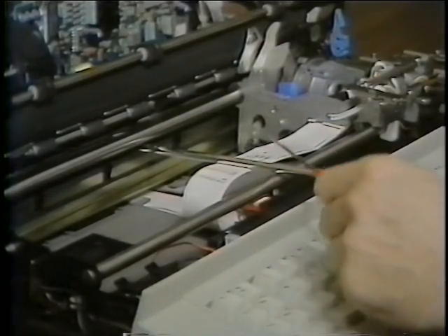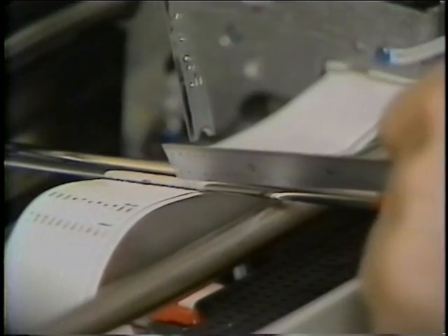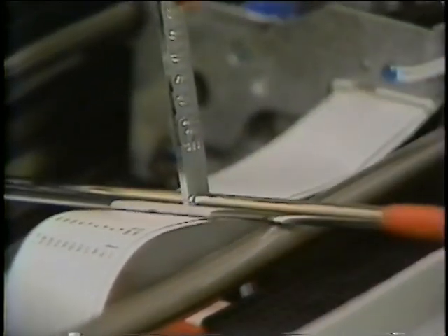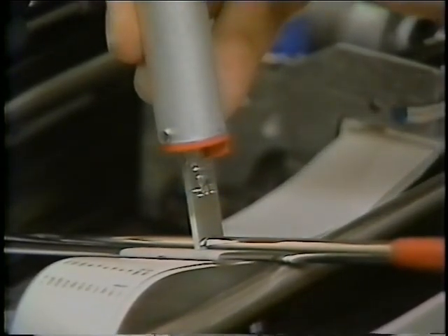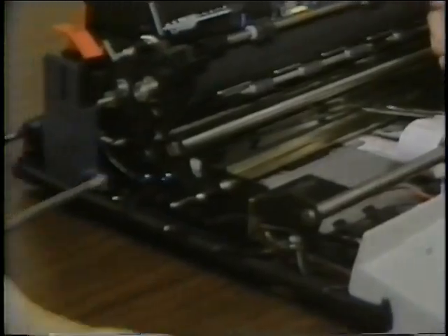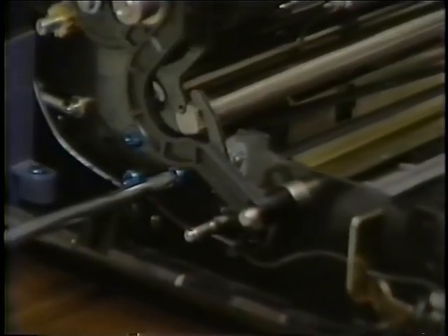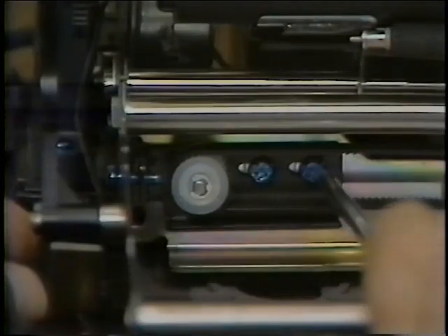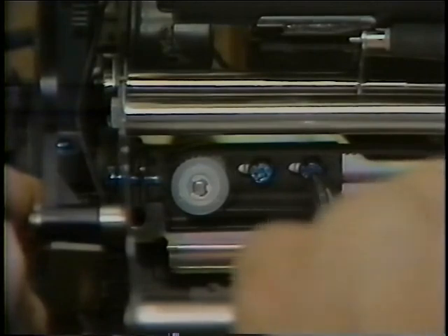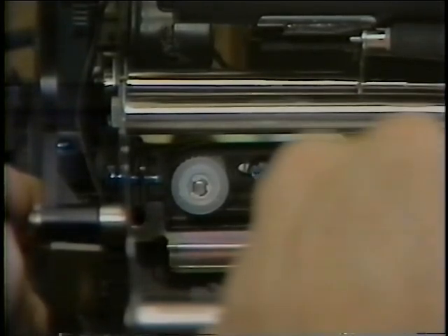front shaft as shown. Place the spring scale on the T-bender 30 millimeters from the center of the front shaft. Apply 5 3/4 to 6 1/4 pounds of pressure on the T-bender at a 90-degree angle. Then turn the adjusting screw in or out so the bottom of the T-bender just touches the bottom transport belt. Finally, tighten the idler pulley bracket. This completes the transport belt adjustment.